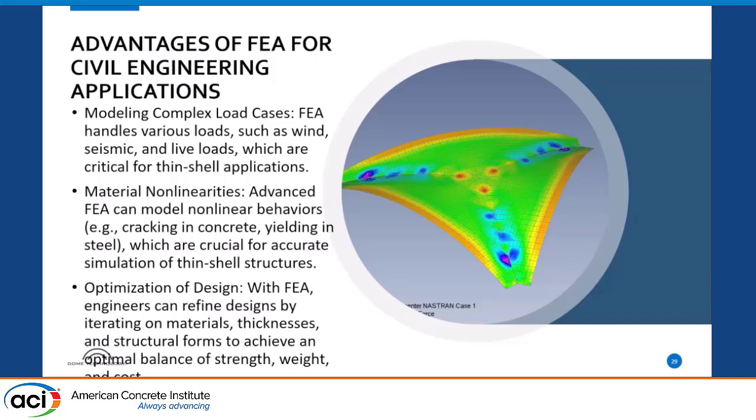Well, we can take into account creep within the concrete, or cracking in the concrete in those tension zones, and the yielding of the reinforcing at those points. Again, there's some trade-off there. Are you going to go through and model that, or is that even worth it? That's something that you kind of have to learn.